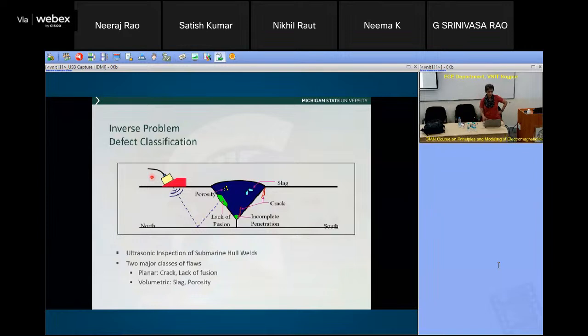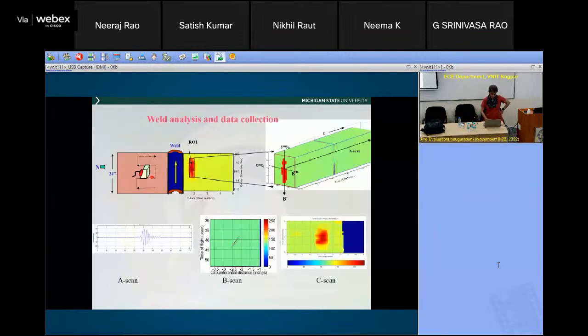And an ultrasonic engineer knows, instead of just keeping in one position, you move it around and see how individual reflections change and use that for reconstructing your geometry. We saw this in the morning. When you do a raster scan like this, you generate an A scan, a B scan mode, and a C scan mode. The A scan is a single position.